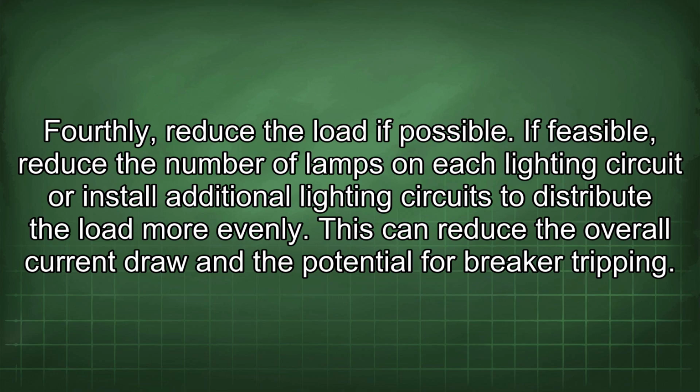Fourthly, reduce the load if possible. If feasible, reduce the number of lamps on each lighting circuit or install additional lighting circuits to distribute the load more evenly.